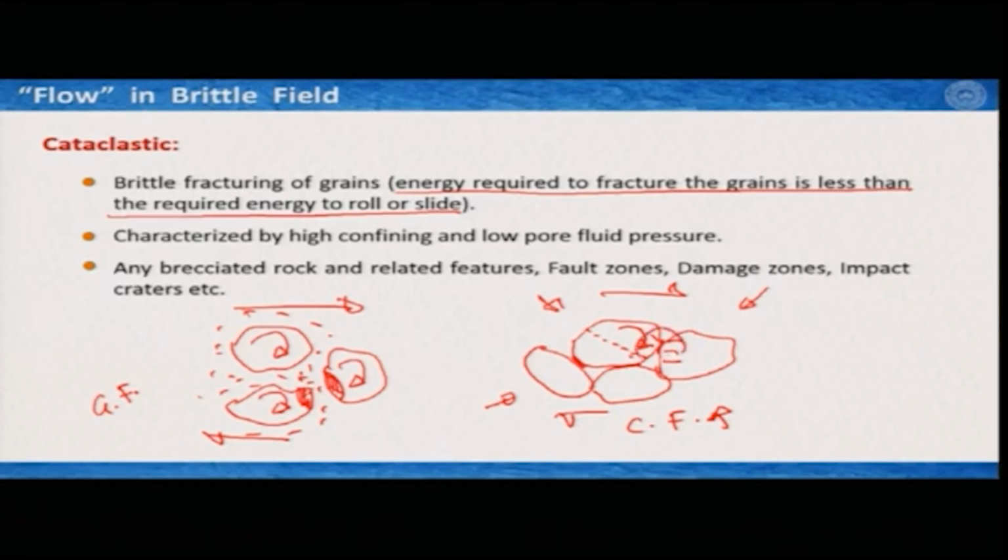And when these fractures happen, they get compacted again, because there is no scope for porosity to stay there unless the grains themselves produce some sort of strong network or strong framework. Then again these tiny small grains try to rotate, but they cannot because of huge confinement. They again produce fracture, and this is how we achieve the cataclastic flow or cataclastic deformation.